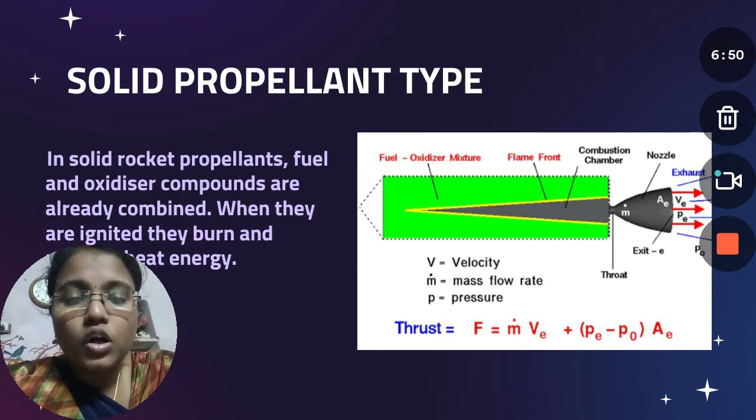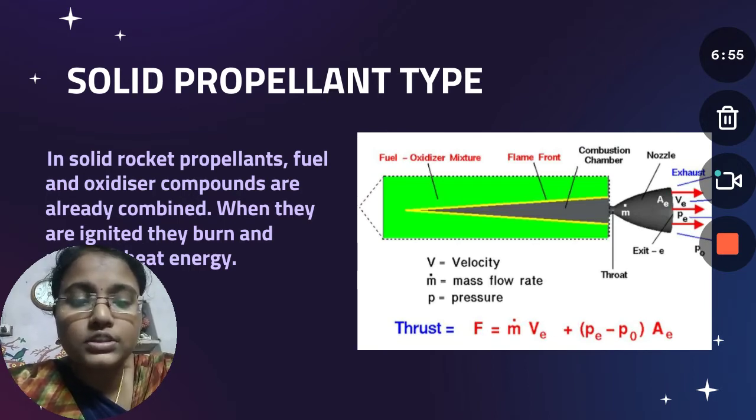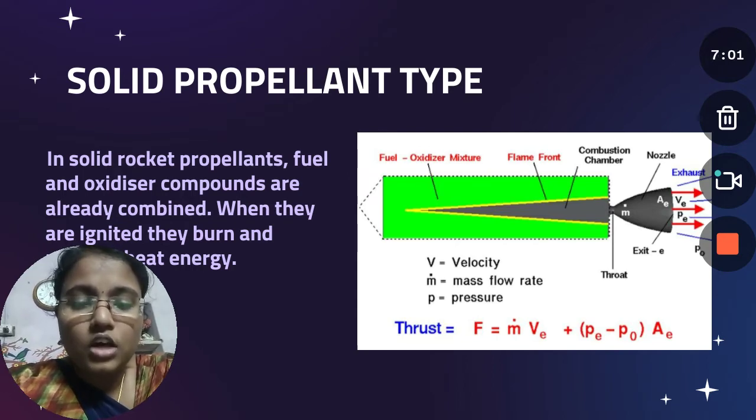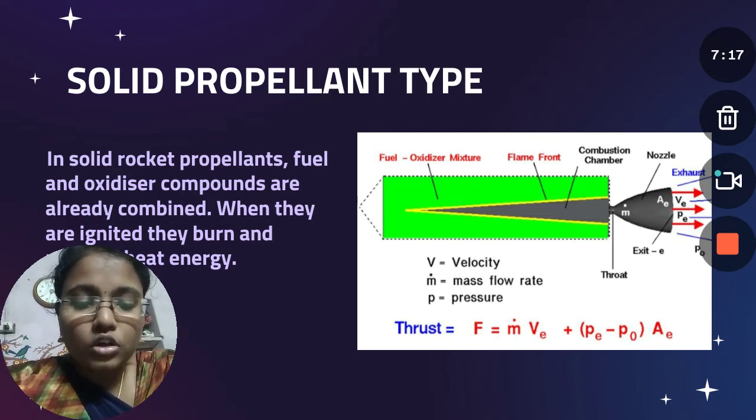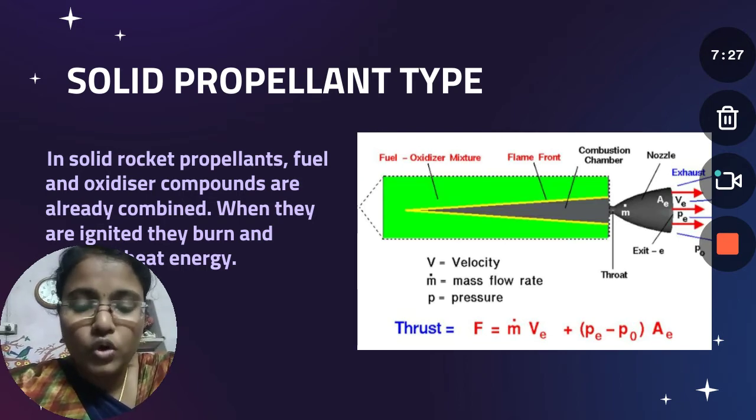Composite propellant. Composite contains no nitrocellulose, nitroglycerin, nitroguanidine or any other organic nitrate. Composite usually consists of a fuel such as metallic aluminum, a binder such as a synthetic rubber, and an oxidizer such as ammonium perchlorate. Composite propellants are used in large rocket motors. It also consists of polyurethanes and polybutadienes as fuel and nitrate and chloride salt as oxidizer.